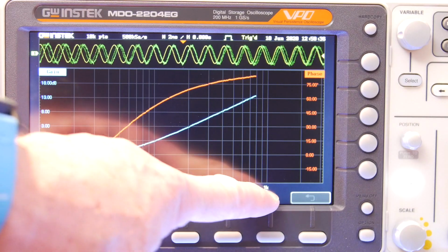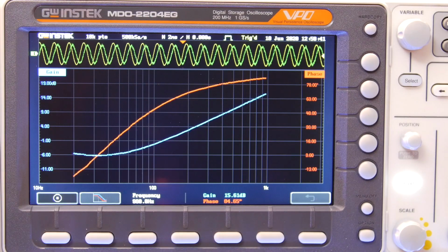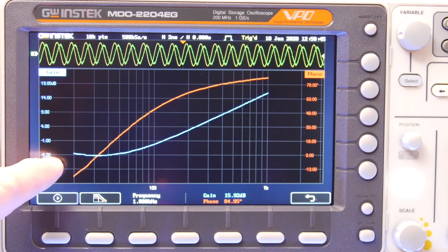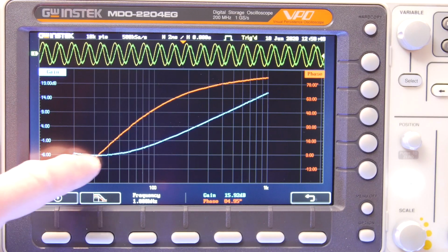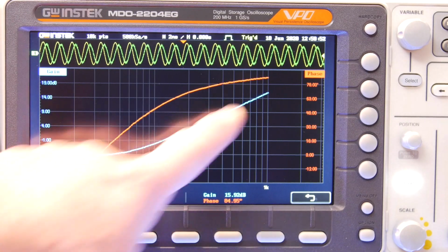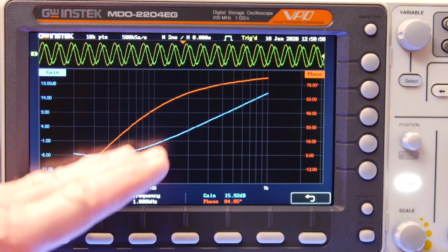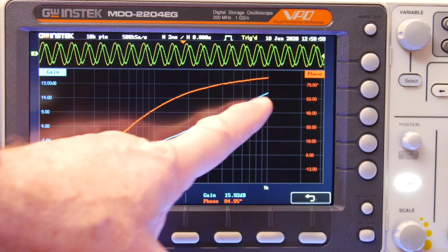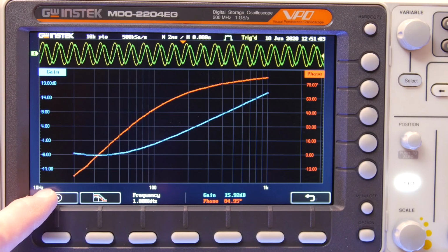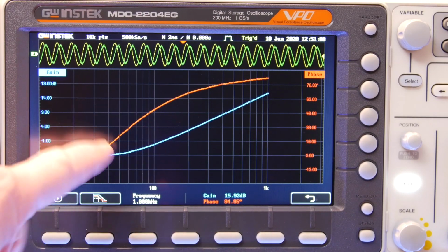Okay, and this is 1 kilohertz, and this is 100 hertz here. And we're just getting there. Okay, if you notice, it started off right around -6, and then right around here it went inductive. So this is resistive where it's flat, and then inductive is this, and they kind of cross. So the inductance curve, if you drew it, you would have drawn it right across here, and resistance you would have drawn across here. And that's where they kind of collide, right about there.